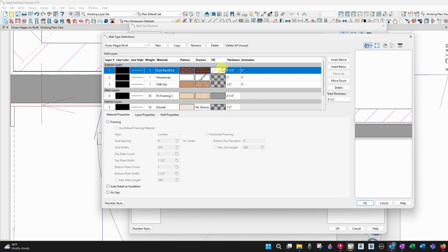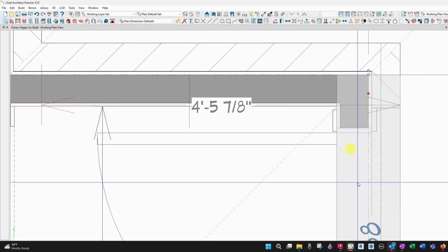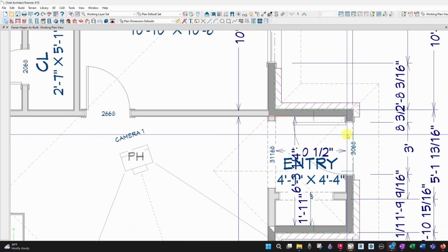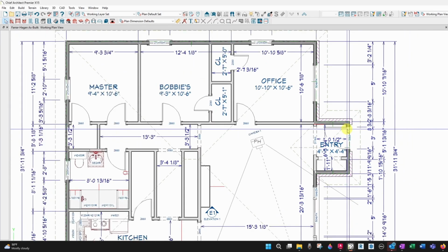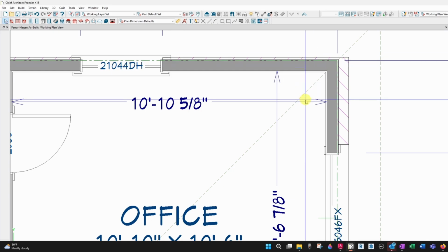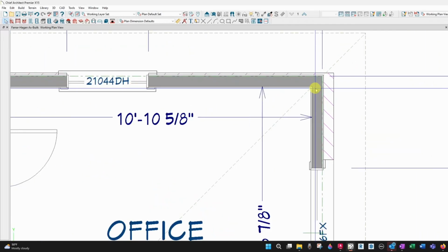There's not a lot of room for moving here, and I can see the brick all the way at the edge. So I think there's no air gap when they put this brick up, which probably veneer put on after the original house sometime in the future by a non-mason. And that can happen a lot in this town, is sometimes some of the newer builders or homeowners that do it themselves